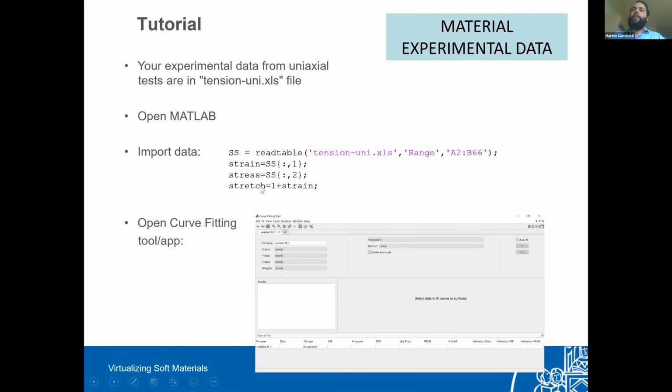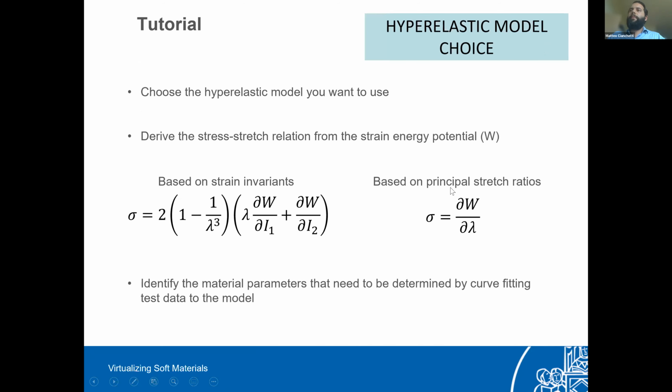So you have the description of these three vectors. Then you can open the curve fitting tool of MATLAB, and you will have a new window with the tool. Then, this is the second phase, and it is about the hyperelastic model choice. We saw several models. Start with one, whatever you like, maybe also on the basis of what we said about guidelines, but for the tutorial, I would like you to test all of them,